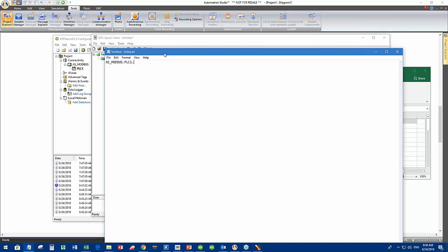Now comes the next point into the equation. What is the address of the PLC register? So normally, if in Koyo was one PLC defined in the Kepware server, I could have written here immediately C1 because I know the register, the internal register as C1, C2.